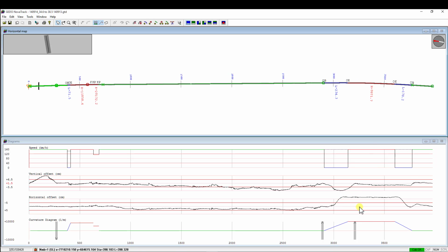So we push the offset down to the required level. We right click on the window anywhere and then select normal edit mode, and you can see we can scroll through the alignment. What we do further is, you see there are some large offsets on the circular curves, meaning the wrong radius or the wrong length. Also, we will adjust the length of the clothoid, as they influence these offsets too.